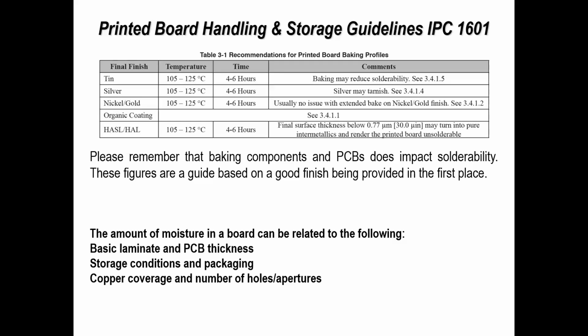So again, the moisture bake out is related to the laminate material type. It's also related to PCB thickness, the storage conditions, and packaging. So the original packaging you received the boards in, if they've taken 1 day or 3 months to get to you by boat from around the world, then obviously there is an impact there. Depending on the packaging will depend on how much moisture may or may not be present inside the package. Also, the copper plating, the thickness of that copper plating, and the thickness of the copper, i.e. the original copper weight on the board, will have an effect. And also the holes, the number of holes in a board, the size of the holes, whether they're plated or non-plated. Each one of these has a small impact on how moisture escapes from a board during a baking operation.